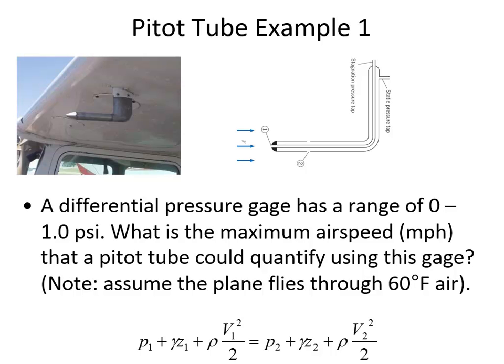We can substitute in the numbers now. V2 is going to be 2 times the pressure difference, which was 144 pounds of force per square foot, divided by 0.00237 slugs per cubic foot, to the 1/2 power. That is 348.6 feet per second.